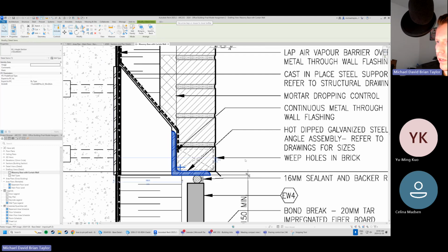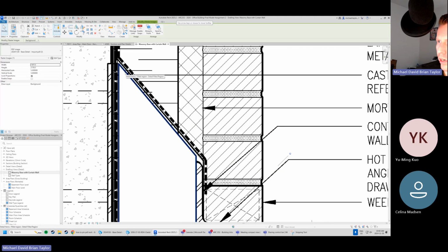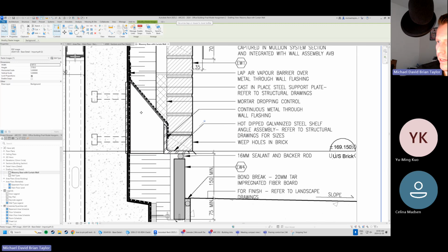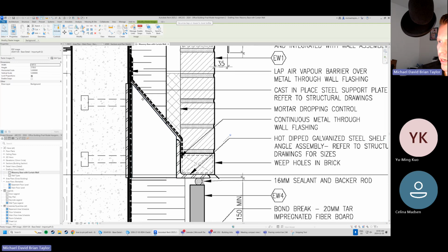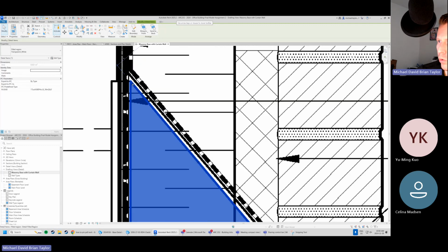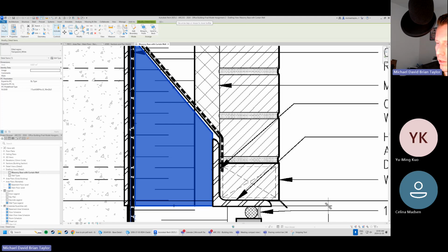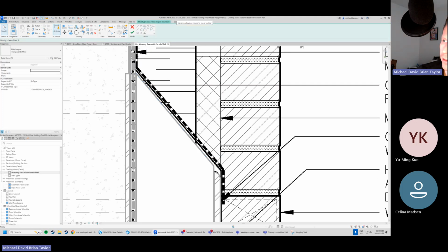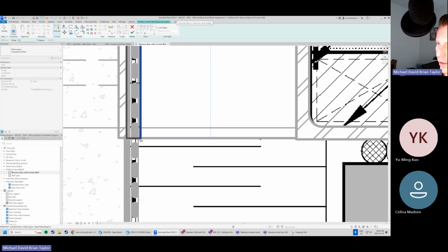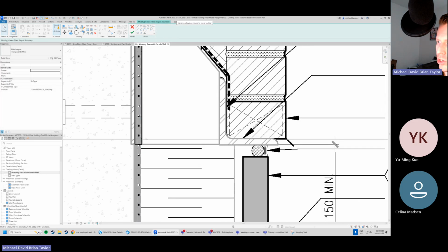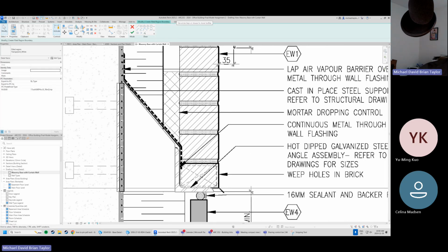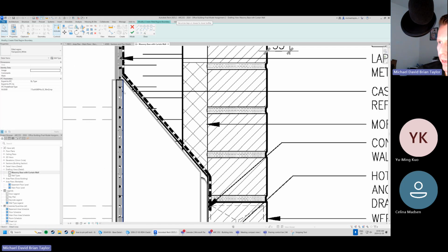And now what we can do is we're actually going to just tidy this up by creating a final one here, which is actually going to link this little piece back to the steel embed plate itself. So I'm going to create similar. I'm going to draw a little final. This is really the edge of the angle that's being welded to our little plate at the back here.